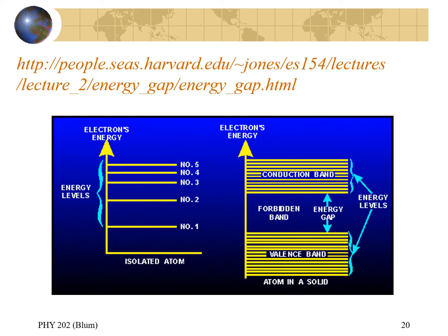So in the picture on the right, we were filling the lower band with electrons, two by two, one spin up, one spin down. And then when we got to the place where we had enough electrons for the solid to be neutral, we found that we had just filled that band, and that made it the valence band, where the highest electrons were. And then the conduction band was separated from the valence band by this gap. That's our main idea behind what makes something a semiconductor.